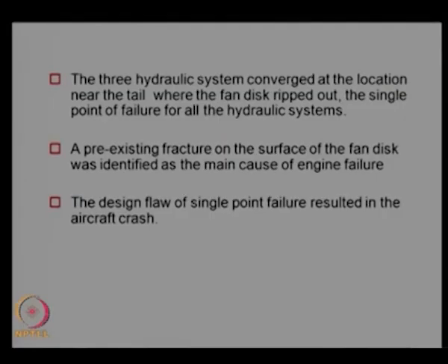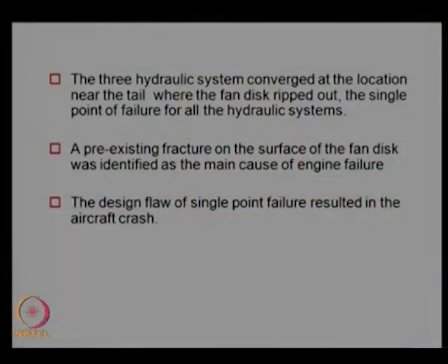That was the cause, because even though all the 3 hydraulic systems were working perfectly, and there were 2 engines powering the hydraulic system, the hydraulic power supply could not reach the control plane actuation points, because this was a single point where all the 3 hydraulic systems converged to give the supply. So this was a single point failure in the system, and this is one of the important points to look at when we provide the fault tolerant system.